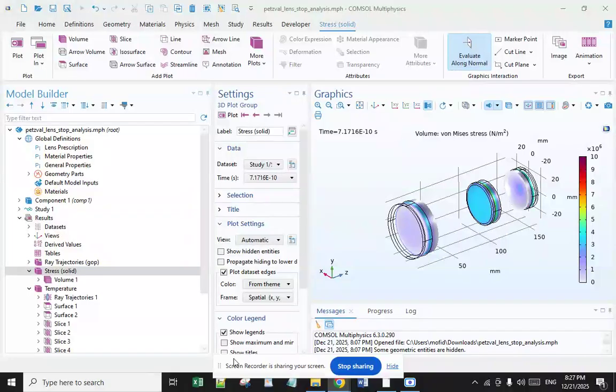The other, non-isothermal model includes a thermo-vacuum enclosure where the exterior temperature is significantly different from the interior. The lens assembly is placed inside this enclosure and is exposed to this exterior via a pair of windows. The resulting temperature gradients and displacement fields within the optical system are shown, as well as the effect on image quality.